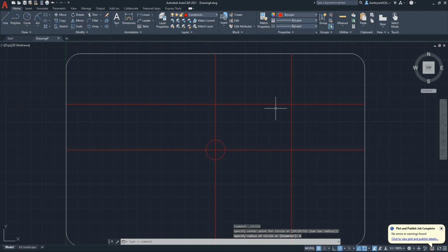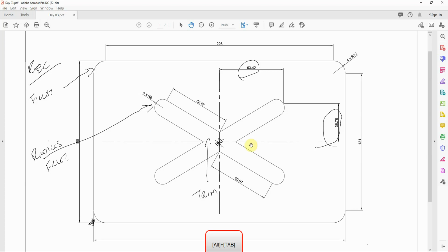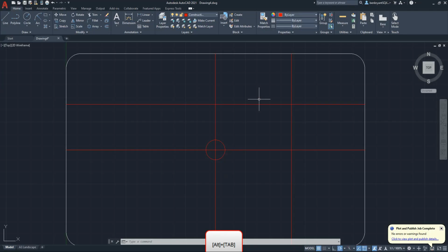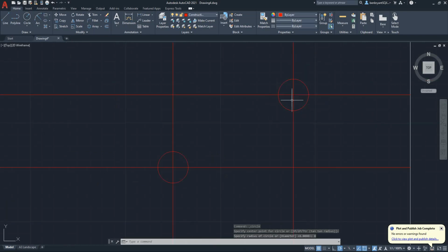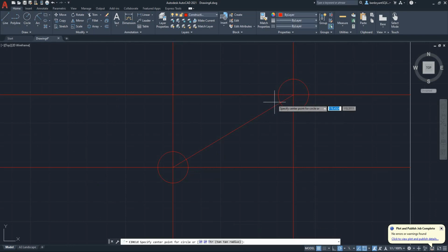Now that's going to give me the rough geometry that I need. This is point to point, so essentially the point has to touch the radius there. So I'm also going to put an R, put an 8 on that side. Now if I use the center point here and draw a line between the two, I've now got a little center point, and what I can actually do is use that quadrant to put an R8 on and then delete that R8, so I'm 8 mil further back, which is what I need, because that's where those points on those dimensions actually meet.